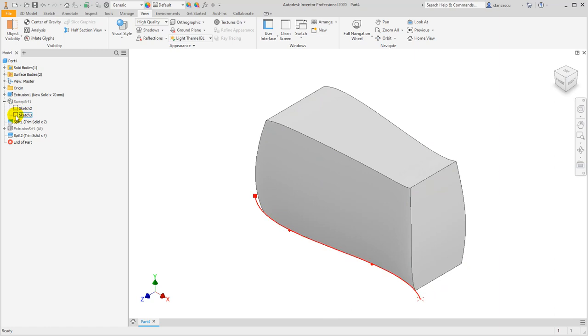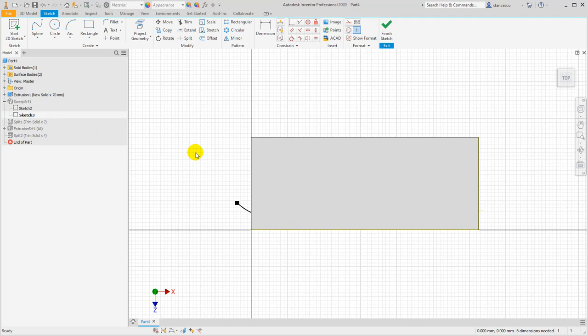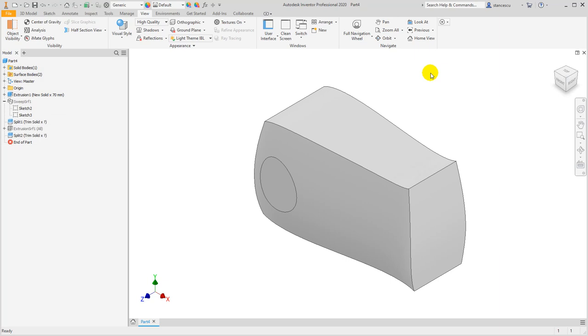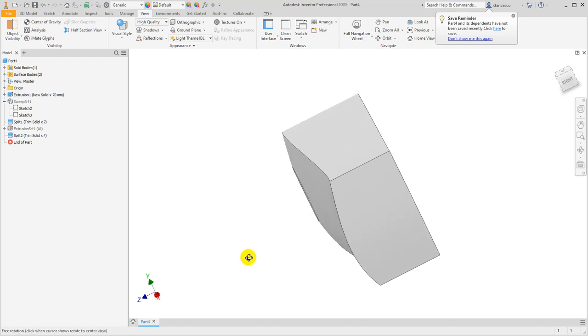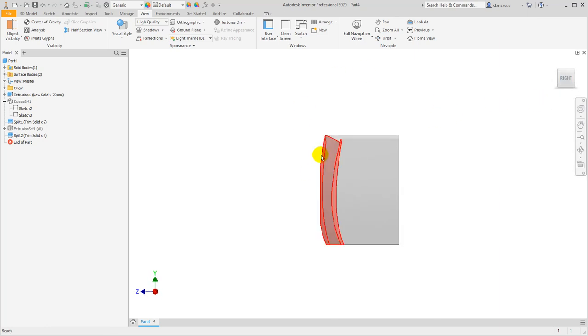modify this curve, double click, F7 to see inside, and I move this very little, finish sketch, and now I see a flat. This is from the original box. I look so, and you see this is flat. Now I know where that relief is